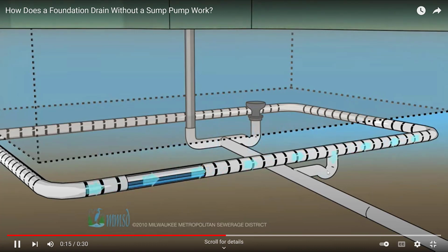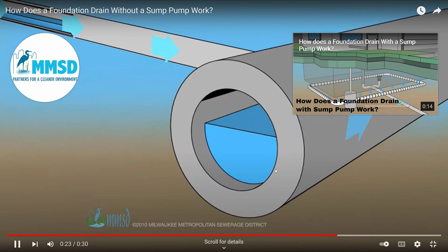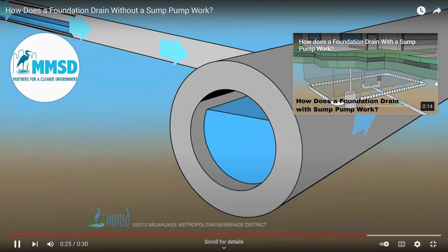In my opinion, one thing wrong with this is, do you see how the elevations here are the same? Theoretically, if this was the case, you could get sewer coming down here and then landing into this if this was dry. That's not ideal. This needs to be up higher if we're going to do it, and needs to come in at a much higher elevation than the flow line elevation of the sewer. Not a big deal, but you get an idea that that's what we're talking about there.